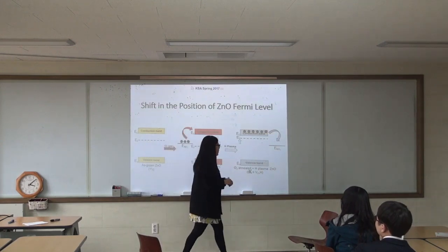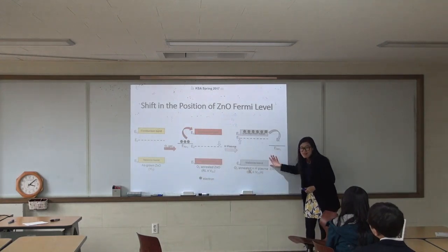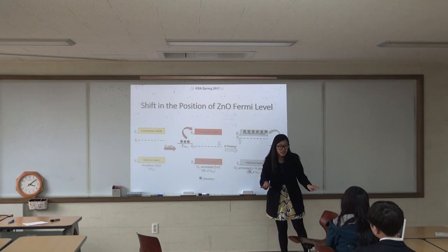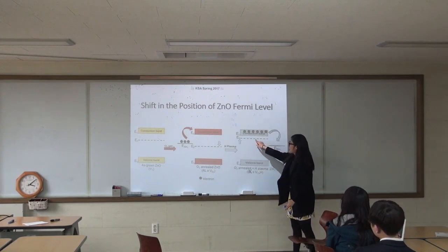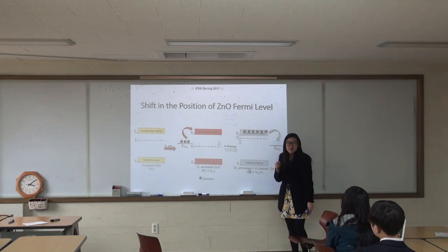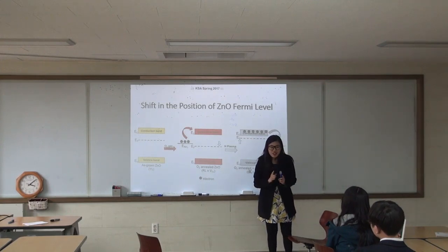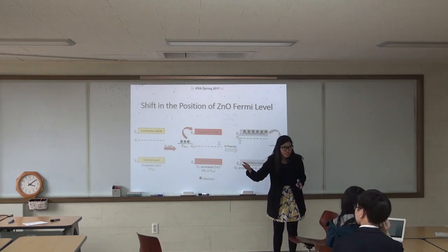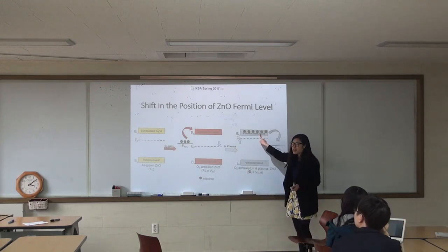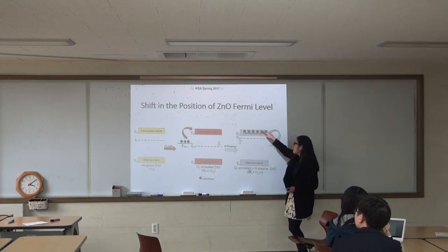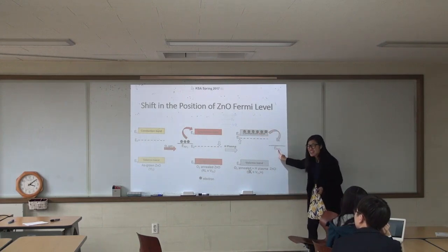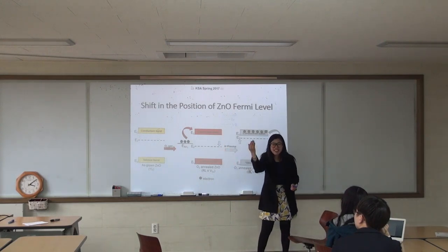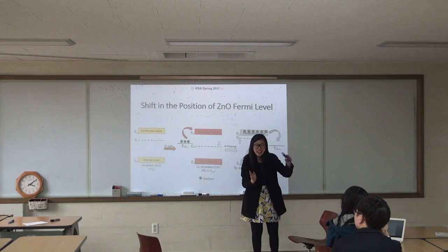But the other way around, when we did hydrogen plasma, we destroyed that defect level, right? So it shifts the Fermi level up more, because everyone agrees that hydrogen is a shallow donor. It's a shallow donor, so it shifts the Fermi level up and up. So then it happened in a different way: electrons from the conduction band flow back to the ammonia gas instead of flowing to the conduction band. That's why the sensitivity signal happens in the opposite way. Okay.